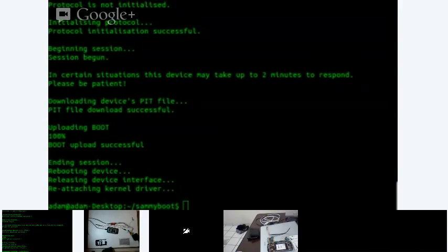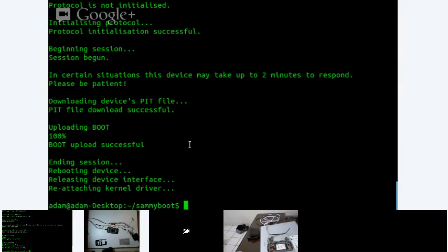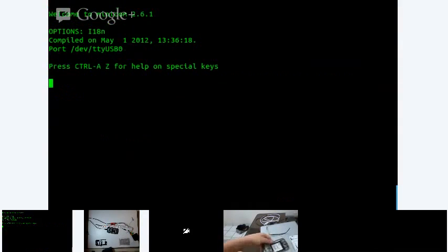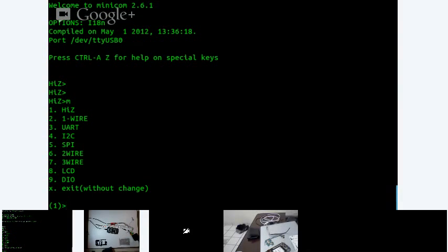Let me switch back over here, and now the way to initialize the Bus Pirate is I use minicom -D /dev/ttyUSB0. All right, good. It's either USB0 or USB1, and I never know which one's which because sometimes my ADK initializes before the Bus Pirate does, and I end up trying to connect UART to my ADK, which doesn't really do much.